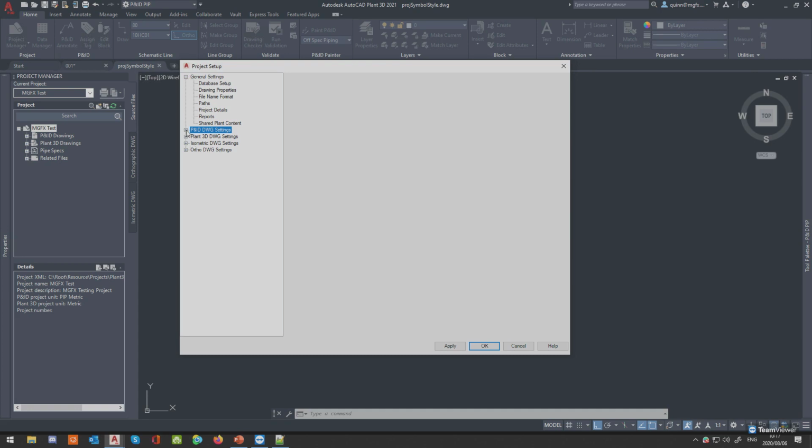So once this is done, now what you'd want to do is navigate to the correct area. As you can see, my nodes were expanded there. If it's not, you just have to find the piece of equipment this is going into. I know, for instance, this is going to my hand valves, but if it was another piece of equipment, I'd have to go, okay, P&ID settings, what does it fall under? Connection, line setting, not interested. P&ID class definitions. Now, I just know this because I do it quite often, but you may need to do a bit of digging to find your way around.